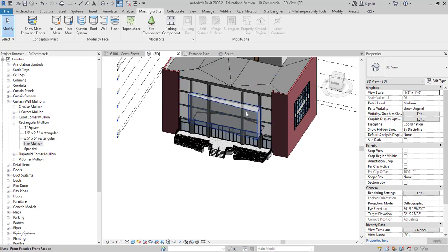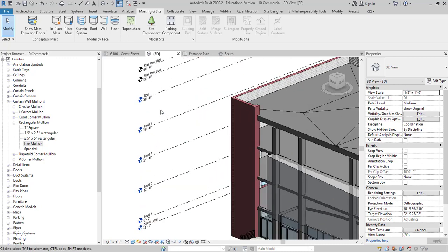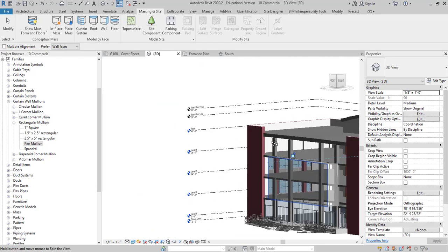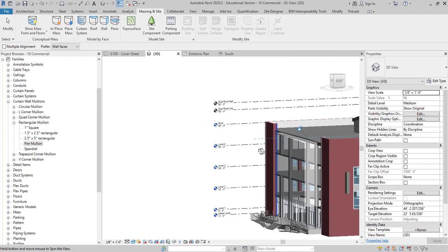What's wrong is the top of this is supposed to come up to the 4th level. So I'm going to go ahead and do a new alignment here. I need to be able to see my level. So I'm going to say AL, align to level 4, this surface. Oops, I guess it's aligned to roof, this surface. What's going on here? Come on now. AL, align to level 4, this surface. I guess it's already lining up to level 4. Then go up to level roof, this surface. There it goes. That's where we want it, up to the roof.